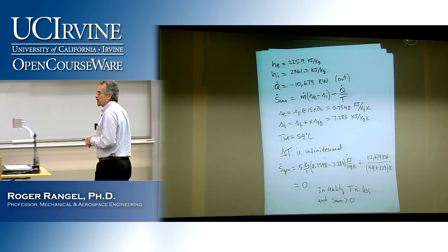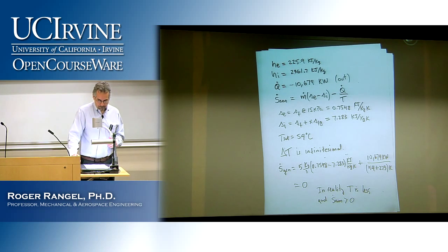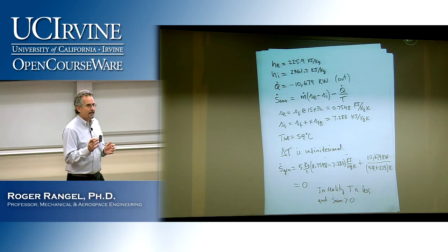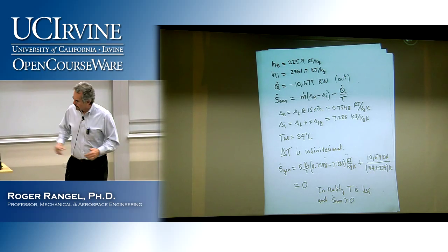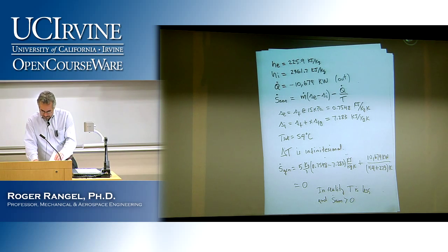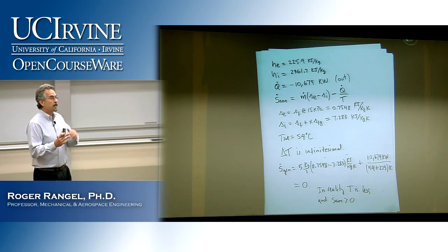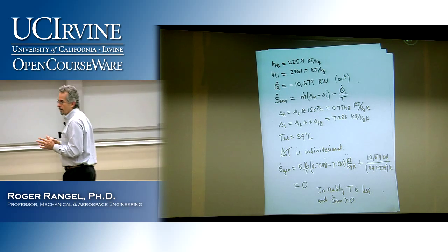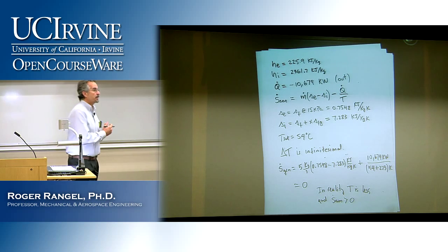And then the number that you get will directly depend on what temperature you use in that equation. So there is a little bit of ambiguity as to what it is, because you can imagine that the temperature of the cooling water will change. I think the actual statement of the problem says that the cooling water comes in at 17 Celsius. I on purpose didn't give you that number at the beginning, but it's in the statement of the problem. Obviously, it'll have to come out a little warmer because it's taking heat from the condensing water.